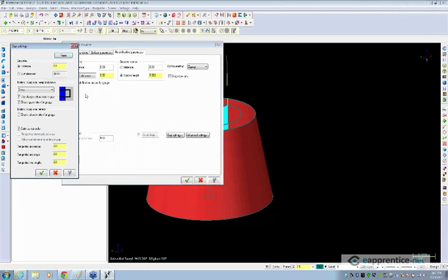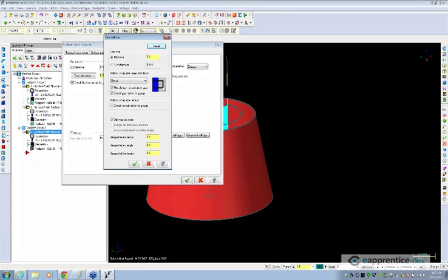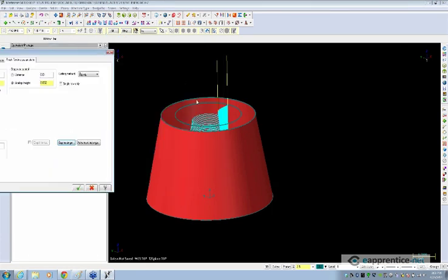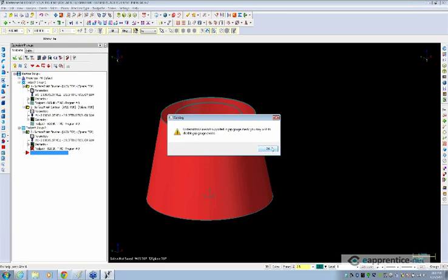So if we go into the gap settings here, gap settings control what happens when the tool is about to do a step down or a step over. So when we look at this toolpath, we're taking slices or using the drive boundary curves of the surface to produce toolpath motion. And what ends up happening is after we complete a pass on this surface, let me change this also. Let's do a 50th step over. That'll help us generate it quicker, and we can take a look at what's going on.